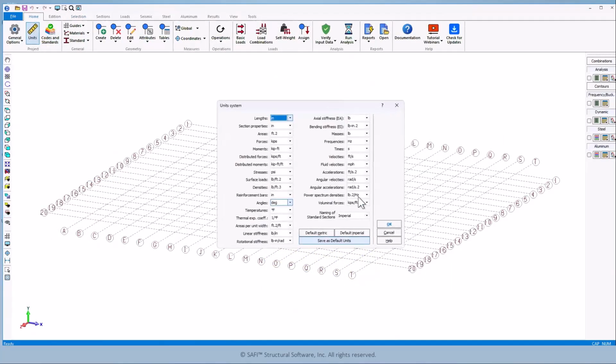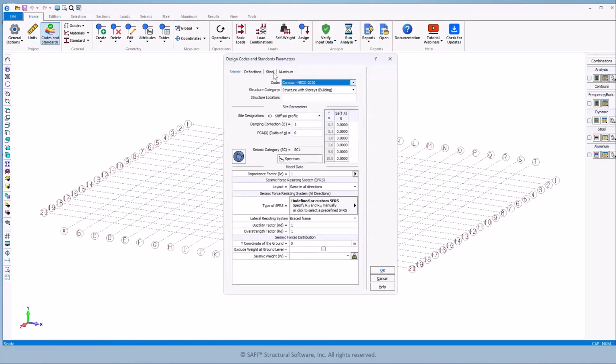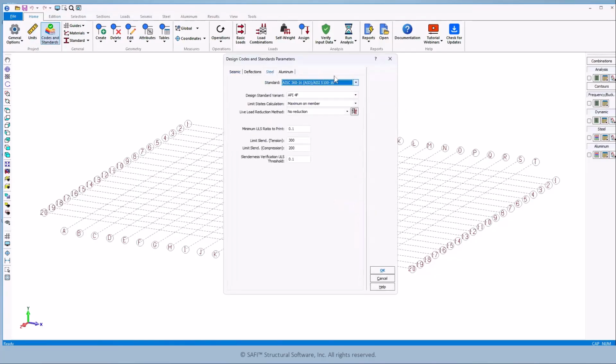When you create a new file in PSE, the first step is to configure your project settings. You'll start by selecting your unit system, imperial or metric, and then choose your design code. For petroleum structural applications, we'll select steel design under AISC. PSE supports multiple versions of the standard, covering both LRFD and ASD approaches. In practice, API 4F projects most commonly use the ASD methodology, which is what we'll select.